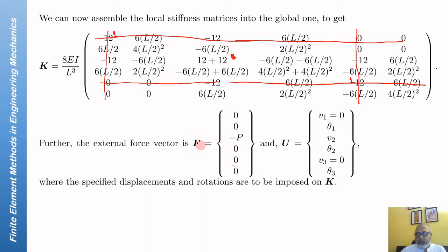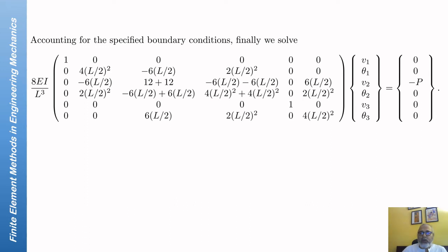So when you calculate the F prime matrix, the modified F matrix, you multiply by 0 the first column, you multiply by 0 the fifth column, and take it to the right hand side, subtract it from F. Since it is 0 for both cases, you subtract nothing from F, and F remains as it is. And as it turns out, this and this are anyway 0, so you don't have to replace them either. But if they were not 0, you would have to replace them by zeros, so that you now have an identity for the first and the fifth equation. So this is what you have to do.